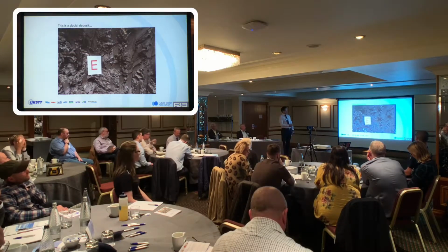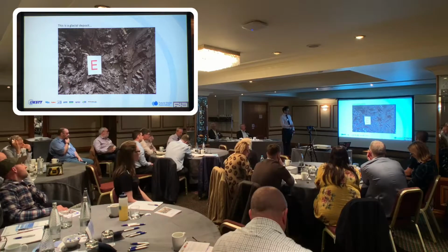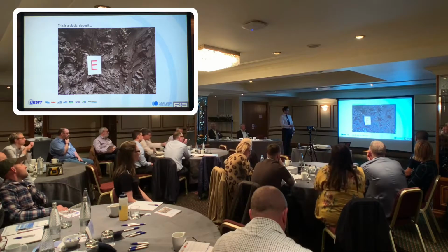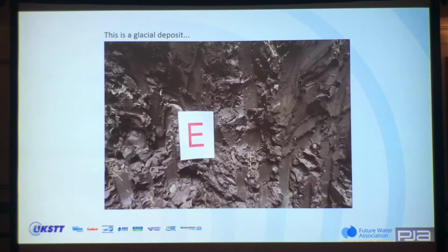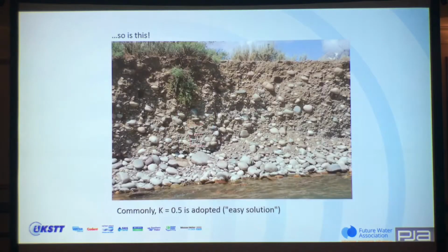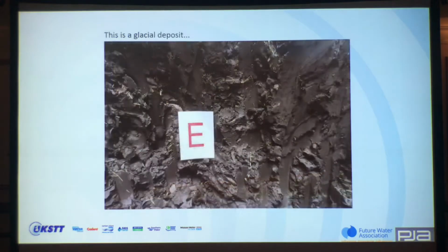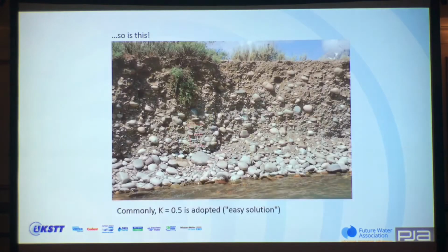Again, same photographs. Glacial deposit, very hard clay. You can see there are actually marks in there from the excavator. So I'd say that's a good stiff clay. And then you've got that material, and you can imagine driving a hole through that. It's probably not going to react anytime soon. There will be some settlements involved, but it'll be a long-term situation. That material is like driving through a cold chocolate, whereas that is more of an Oxo cube. As soon as you drive through that, it's just going to fall to bits.